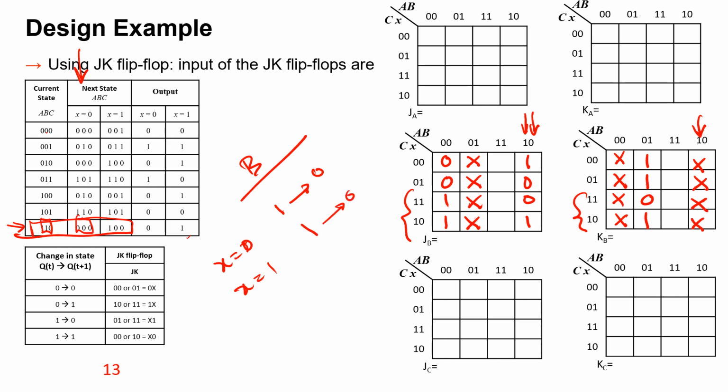In both cases, B becomes 0 from 1. All right, 1 to 0 means here x, 1, x, 1. And I don't have these two anyway, which would be x, x, don't care. So let me do those with a different color just to make sure they're coming from somewhere else, because we don't have that in our transition table.